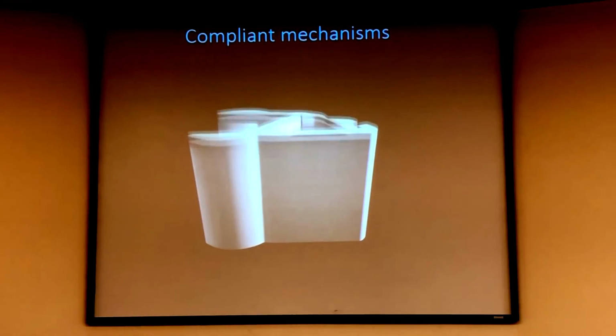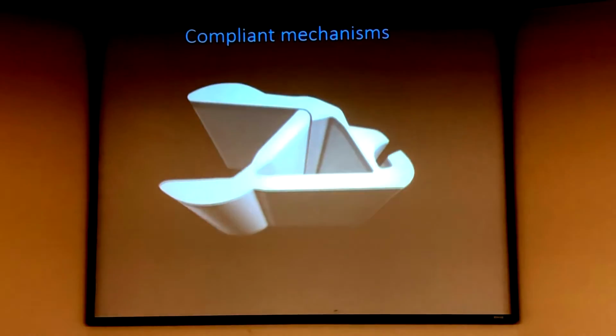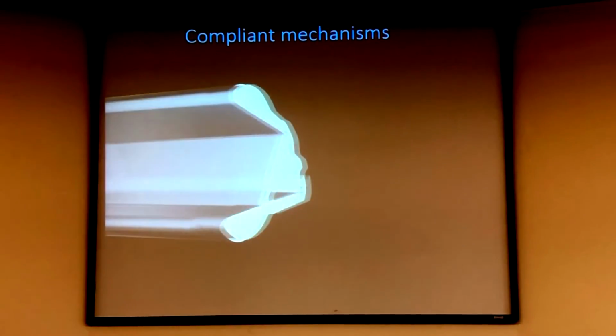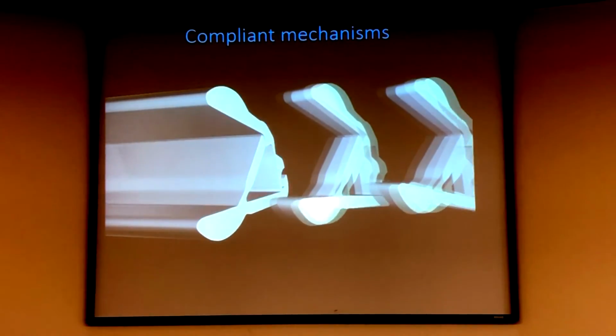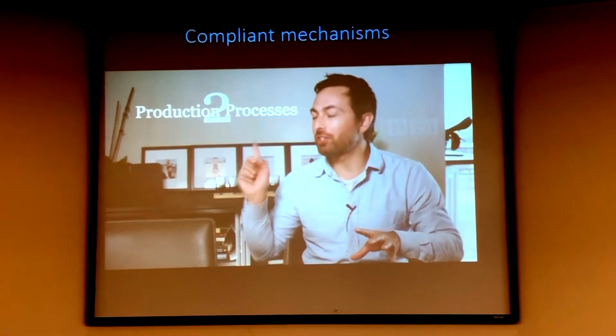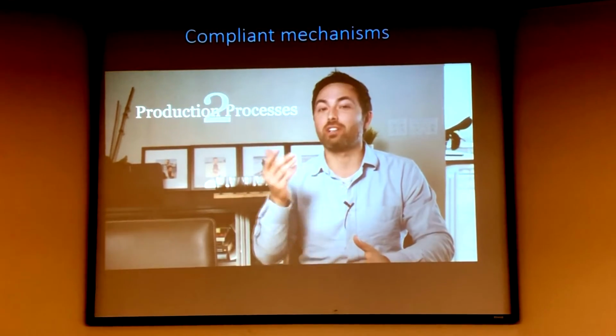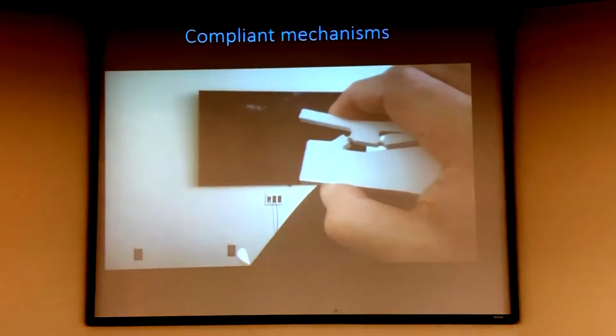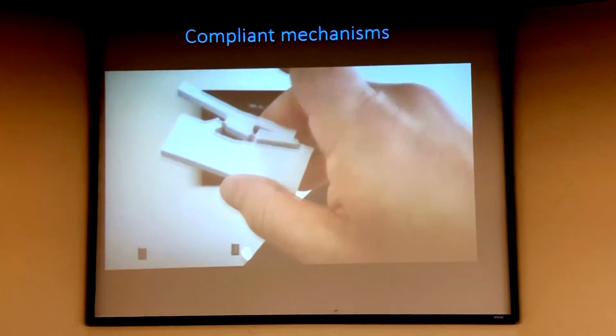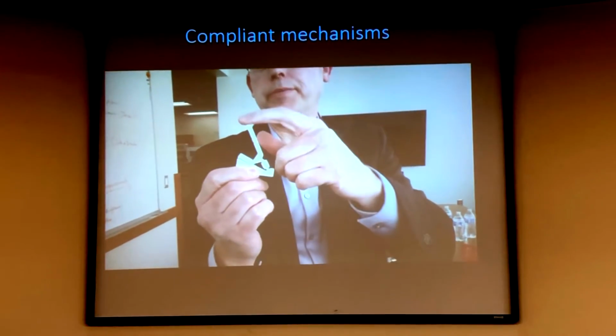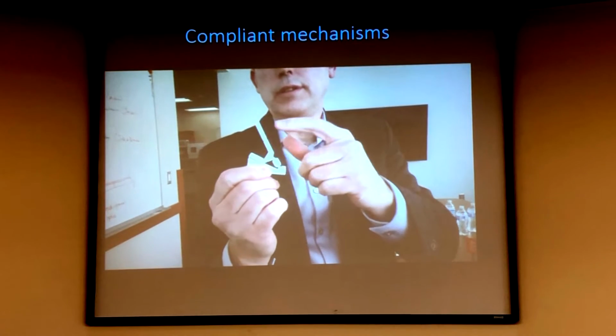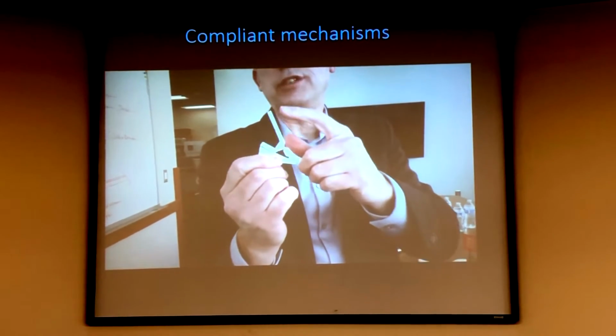Another thing is, because of its shape, you could extrude it and then just chop them off. That would be cool. So the simple design allows different production processes to be used, which lowers the price. These switches, for example, achieve in one piece of plastic what is normally done with springs, hinges, and many rigid plastic pieces. Also a good fidget device.